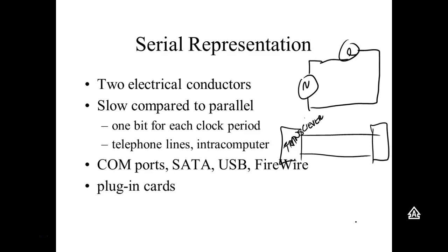Well, it depends. In computers, it would be 16 wires. Because what happens is we're trying to run 2 wires side by side. Anytime I try to put a current into this one and they're right next to each other, it would induce a voltage into the next one if it was a signal wire, if we try to use one ground or one common. But if I use a ground between each signal wire, then this can't induce a voltage through ground, right? Does that make sense? So normally in computers, if we're sending the information parallel, we do it 2 wires per bit. So about 16.